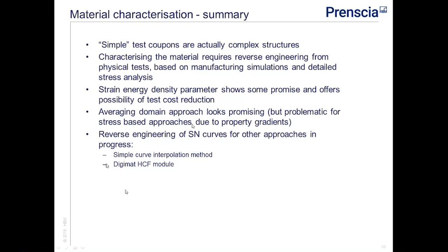We've got a bit of work to do on the averaging domain approach, and work in progress is reverse engineering of SN curves for the other approaches as well. That is for our simple interpolation method and the Digimat high cycle fatigue method. So I'm going to explain these a little bit more in the next few slides.